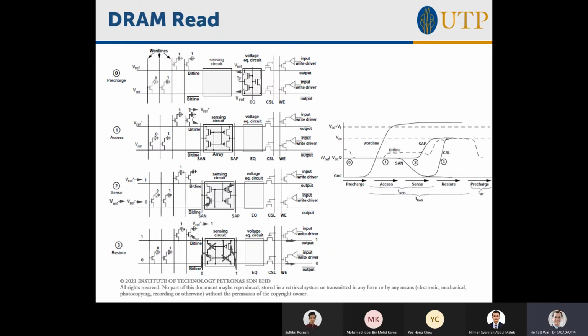Initially this line and this line were the same voltage, so this transistor is turned off. But when VREF goes up ever so slightly, this voltage here is going to be greater than V threshold of this one. This transistor is going to turn on.